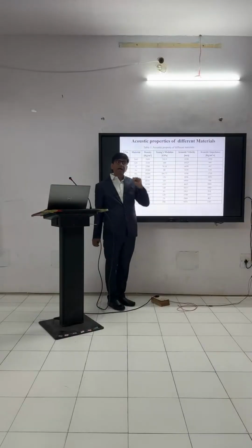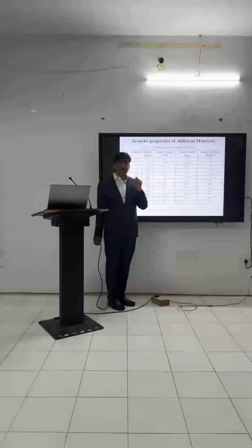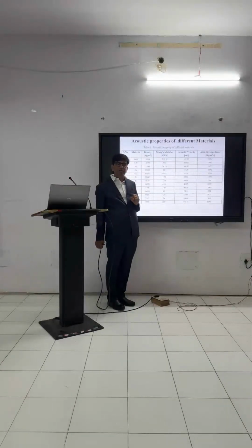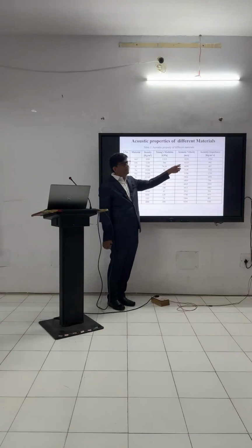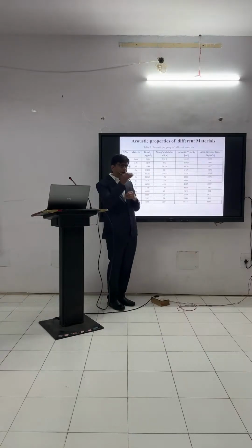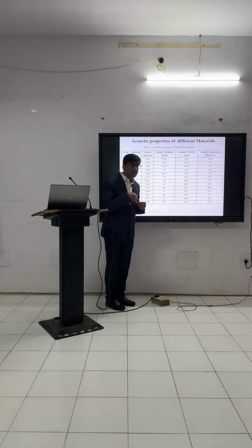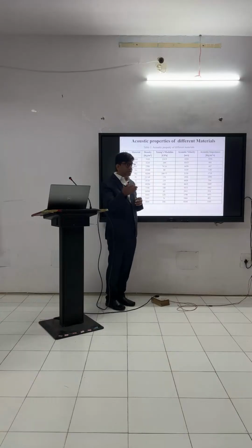So if I take a high frequency resonator, which material will I choose as the piezoelectric material? Aluminum nitride. Then you have to decide how to choose a particular type, because it depends on what frequency you are targeting. For example, you are designing a 5G filter or 6G filter.